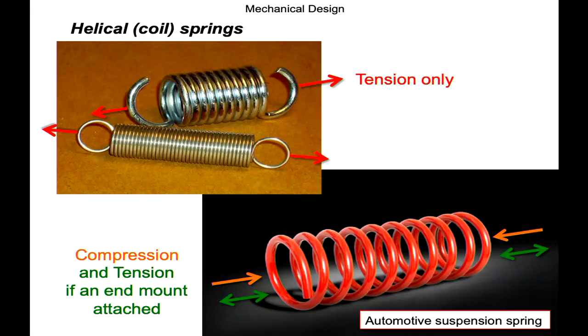That's okay, I don't want to waste your time. That bit on the end, just contemplate. It's going to have to absorb that load as well, and it's going to deflect a little bit as it absorbs the load. What we've essentially got is three springs in series.